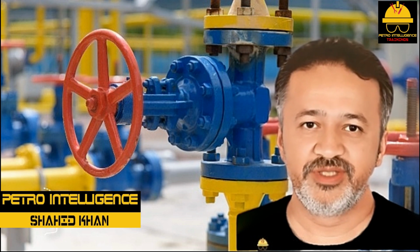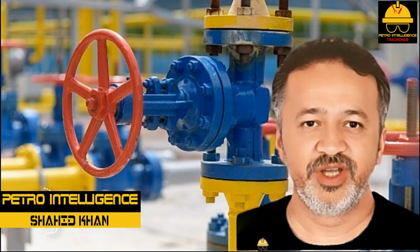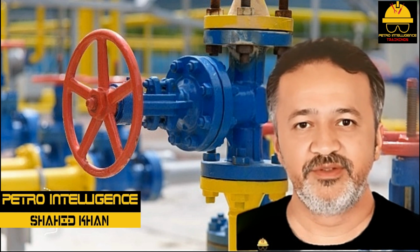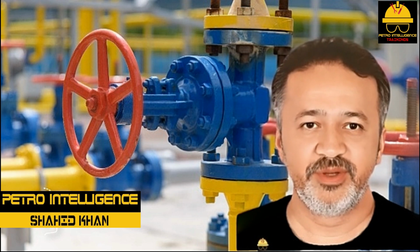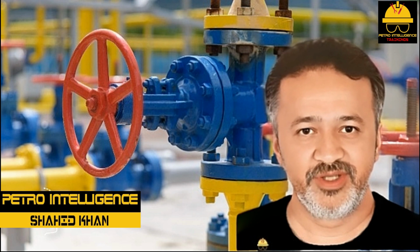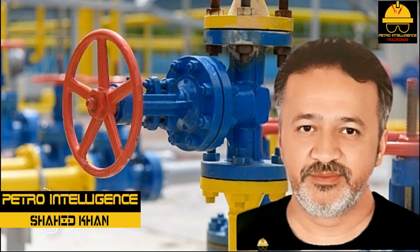The three major differences between a relief and a safety valve are liquid versus gas service, the pressure response time, and a larger exhaust port. Relief valves are designed to lift slowly, whereas safety valves tend to pop off. Because the exhaust port is much larger in a safety valve, it can release more flow at much lower velocities. This feature keeps the trim from being damaged.